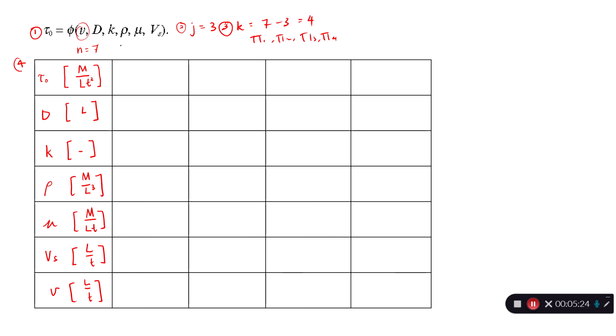So step 4 is we start to remove the dimensions step by step. Before we begin, we already have a dimensionless variable, which is this. K is already a dimensionless variable, so set this as one of your pi. This will no longer be part of our table.